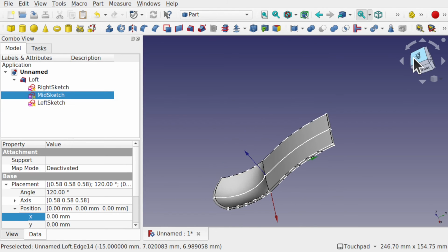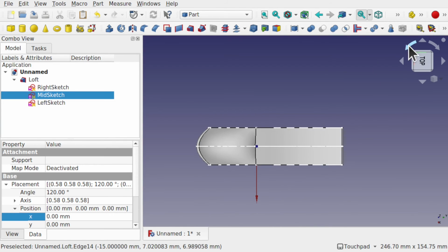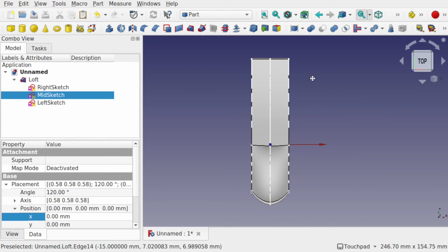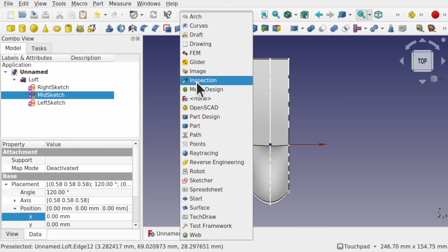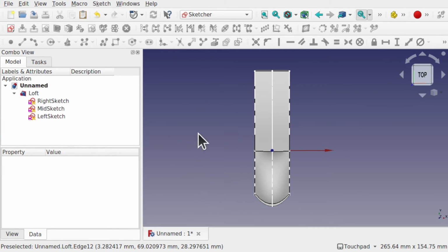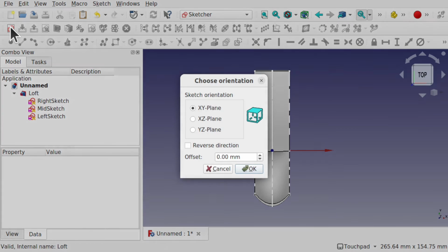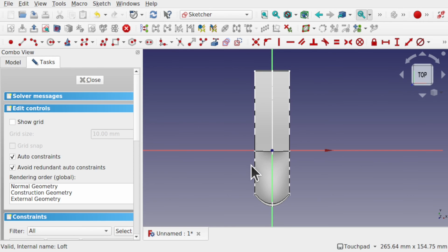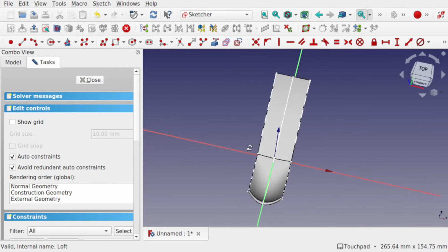Now let's come to the top. And it's best to bring us around in line with the top. So we've got our vertical and horizontal alignments the same as our scene, and come over to the sketch. We're going to create a new sketch, so make sure nothing's selected and create new. This is looking down and this is going to be the profile of the spoon looking down onto the spoon, so from the XY plane. Hit OK. Now we start sketching the spoon.